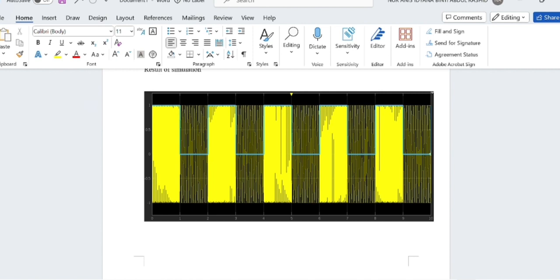I will now show you the Simulink model for FSK modulation and demodulation, which provides a visual representation of the process we've discussed. The model includes key blocks such as the data source, pulse shaping, sine wave, product, band pass filter, and envelope detector, which are essential for simulating FSK modulation and demodulation. The Simulink graphical interface allows for a clear and intuitive representation of this process, making it an invaluable tool for understanding and teaching digital communication concepts.